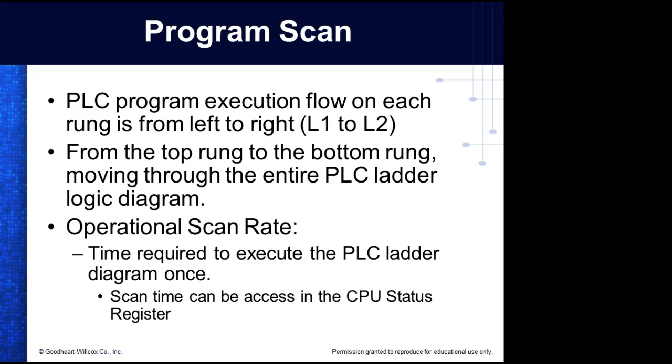Well, you can try some tricks because we had big problems when we first started using these things because the CPUs wasn't that fast. And you'd get extremely long programs and that dang thing would miss inputs. Because you pressed a button and it was scanning up here instead of down to your input. It would literally miss inputs. So we had to do tricks. We had to do little things that we'll talk about a little bit if you take the PLC2 class. But now we usually don't have to worry about that.